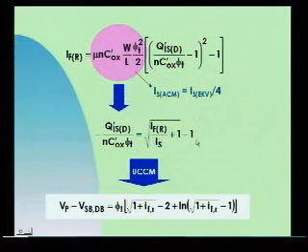And so we can substitute this into the UCCM, and we finally have the single expression for the IV characteristic of the MOSFET in the ACM model, which is very similar to the expression of EKV. You can compare both. The difference is very little.